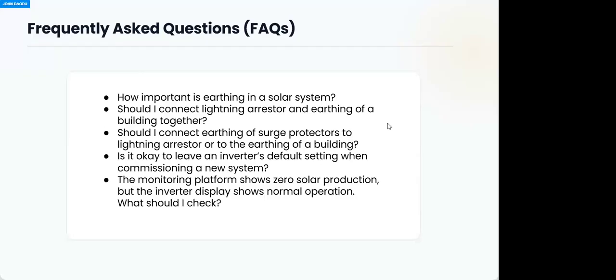You see the battery voltage, you see the charging current, you see the voltage of the solar panels. You see all those three things. If it's working properly and you are able to see all those when you press the button, then your system is okay. But you can check settings to see whether there is a way to set it such that, without pressing anything, you will see the display of what you need to see. Some charge controllers are like that. Some you need to press a button and scroll there to see it. So that's it.